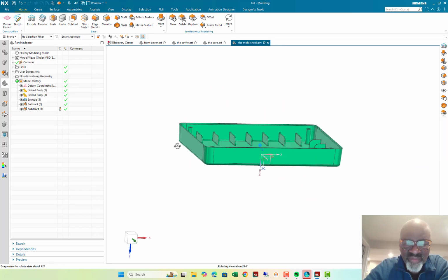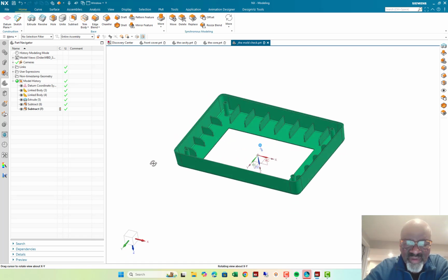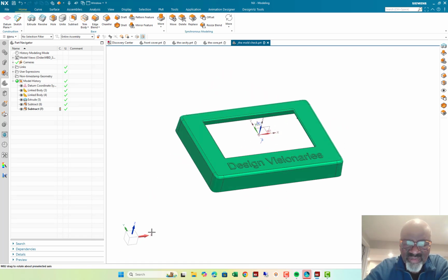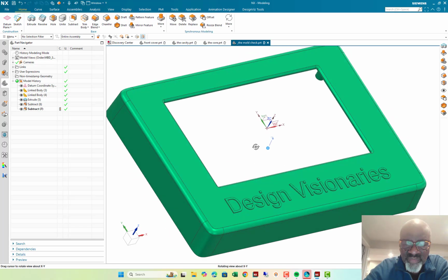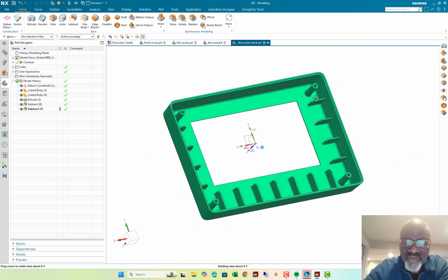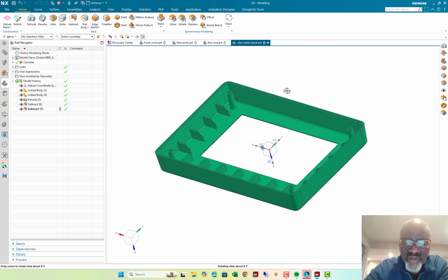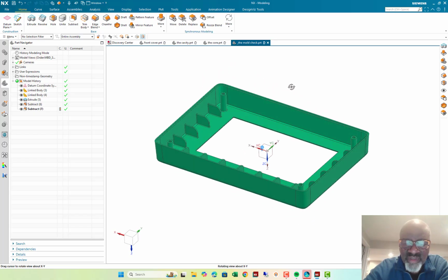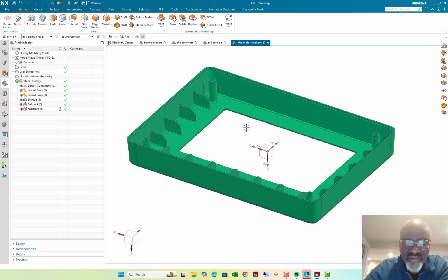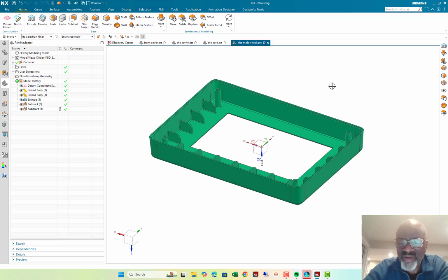Isn't that wonderful? So there you have it. That will be the result. So you could literally 3D print your molds, get a vacuum chamber, and make a reservoir above the two halves, and the resin will flow. Maybe I'll do that in another video.